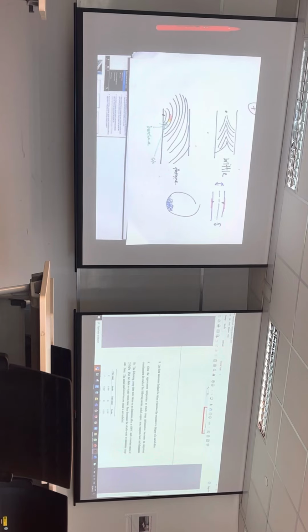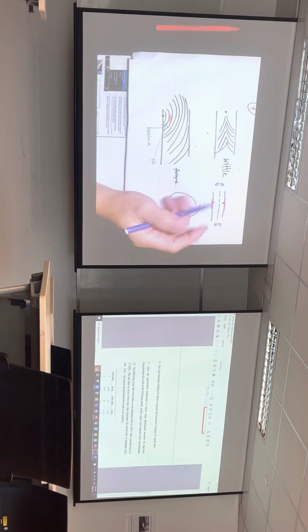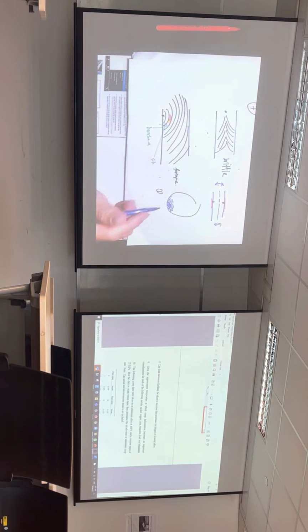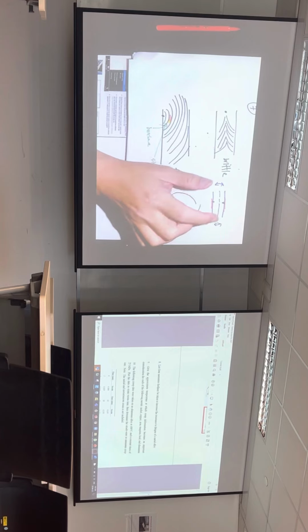First and foremost, you need to understand that a lot of fatigue failure can come from the surface. So you want to design something that makes sure this does not happen. How do I make this not happen? The first thing is surface finish. You want it to be as smooth as possible, nothing rough. For example, if you look at aircraft, everything tends to be very shiny and well polished, not because they want it to look nice like a mirror, but because they want to prevent fatigue failure.